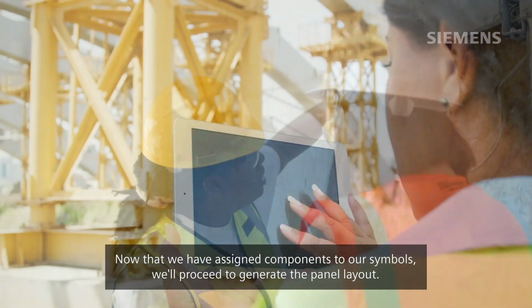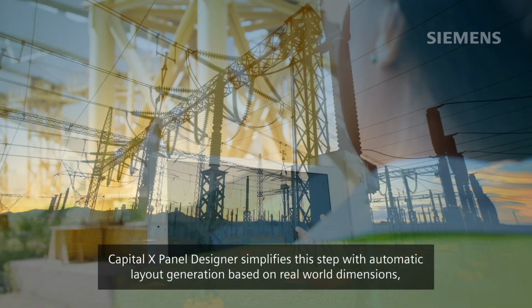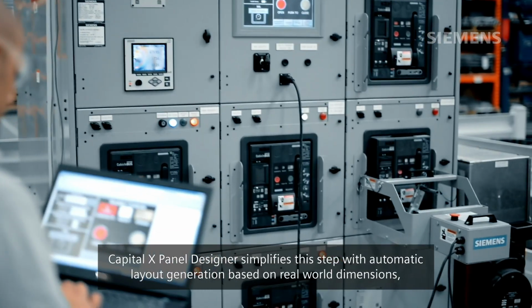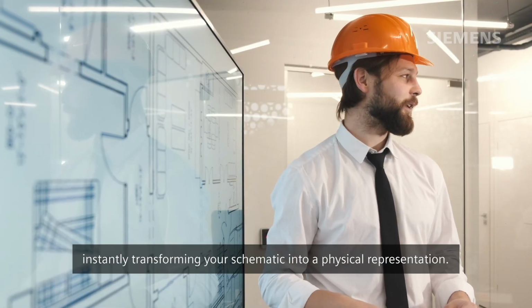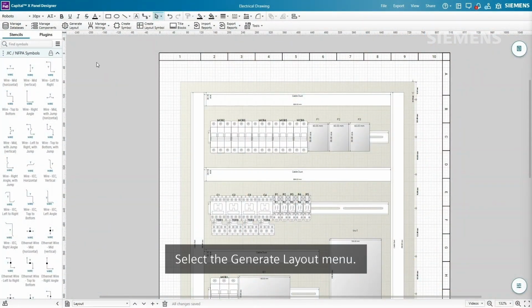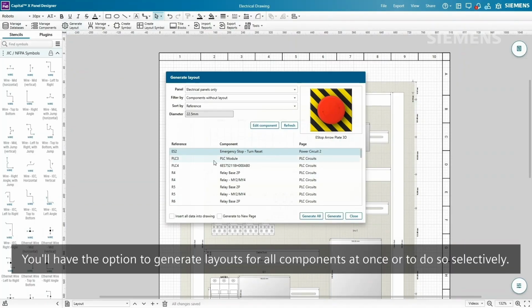Now that we have assigned components to our symbols, we'll proceed to generate the panel layout. Capital X Panel Designer simplifies this step with automatic layout generation based on real-world dimensions, instantly transforming your schematic into a physical representation. Select the Generate Layout menu. You'll have the option to generate layouts for all components at once or to do so selectively.